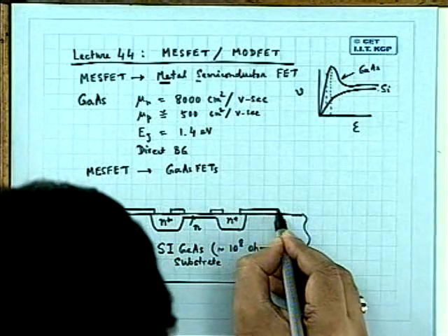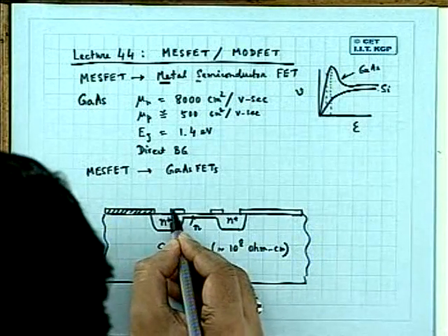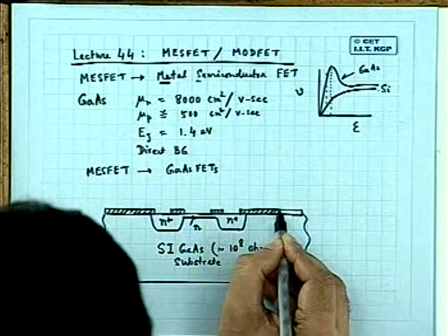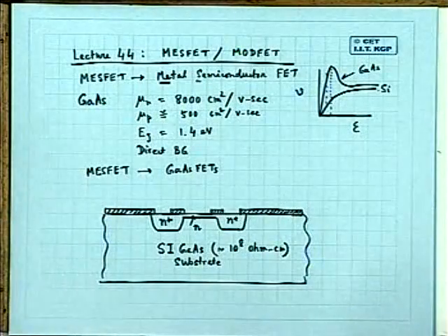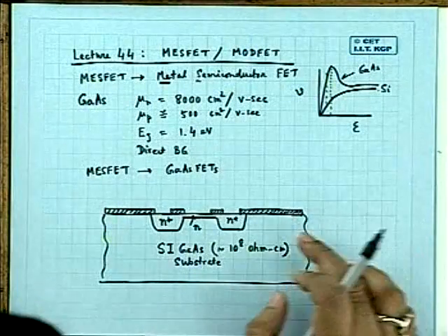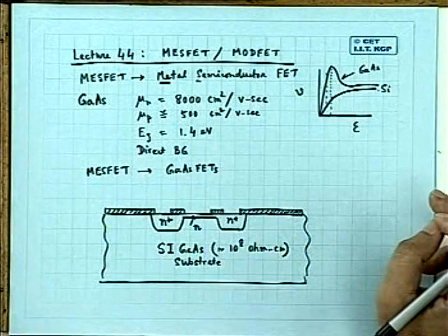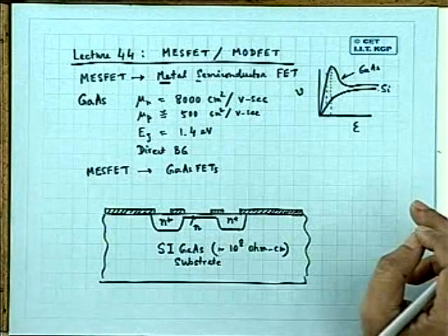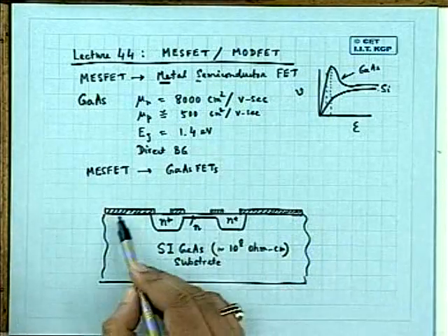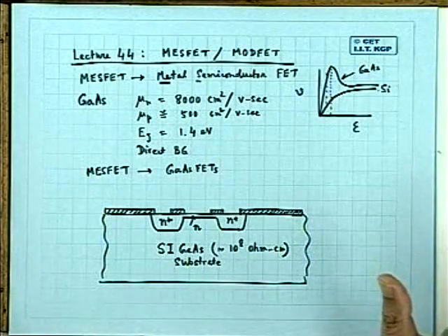Gallium arsenide technology is quite different from silicon technology. In silicon, you remember that these oxides could be grown simply by treating in an oxygen or water atmosphere, called oxidation, which is not possible for gallium arsenide. You have to deposit a film. Typically, silicon nitride is very popular for gallium arsenide, or PSG glass, sometimes oxide, etc. But silicon nitride is very popular. So you deposit silicon nitride and pattern it in this form. This will work as a passivant as well as a mask.